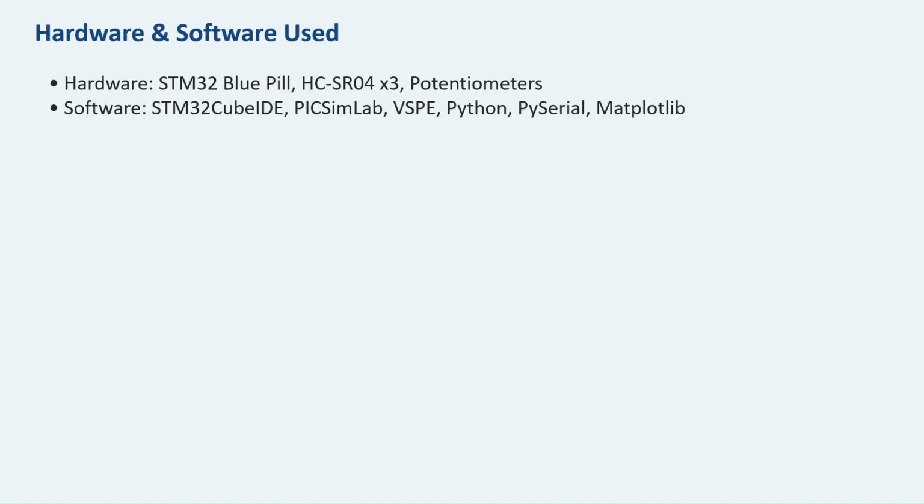To simulate the driver inputs, 4 potentiometers were used. The connections were given as PA1, PA2, PA3, and PA4. We'll see that by going to the STM32 IDE, but initially a brief introduction. The first potentiometer is connected to PA1, which simulates the accelerator pedal. As the value increases, the speed also increases, and the torque and power increase as well.